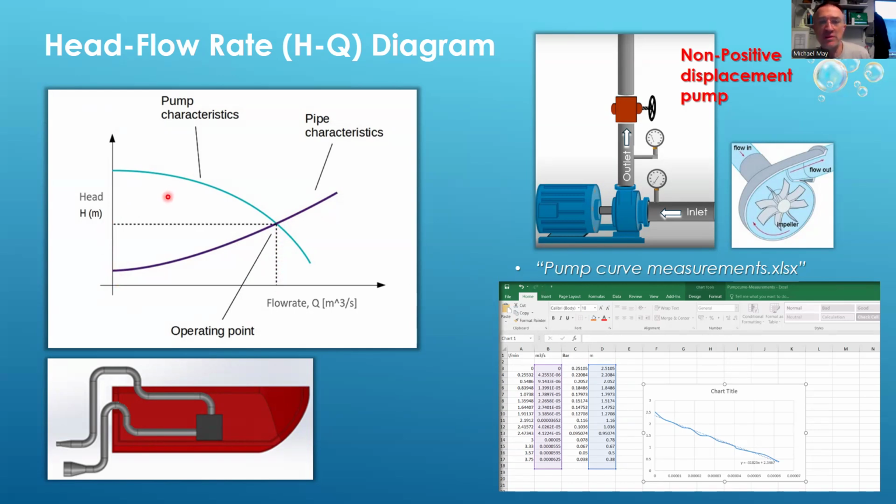So how are these characteristic curves formed? Well, let's start with the pump characteristic curve. If you switch on your centrifugal pump, it'll draw fluid in through the eye and expel it out the outlet tube. While it's running, if you momentarily switch the outlet valve off, keeping the pump running, the pressure will build up across the pump. And in your case, it's 3 meters of water pressure. You can do this momentarily with a centrifugal pump because it's regarded as a non-positive displacement pump. There's clearance between the impeller and the housing. So you get maximum pressure at zero flow rate.